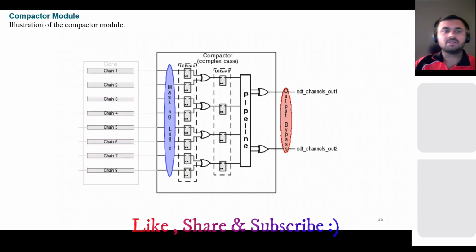Then you have the compactor module, as I told. From the core chains, the output goes to this masking logic. If there are any X's in your chain, it will mask that chain. Then you have again these lockup latches and then these XOR gates. Then you have pipelining to make it faster. And then you have the EDT channel out, where the output from these chains will come.